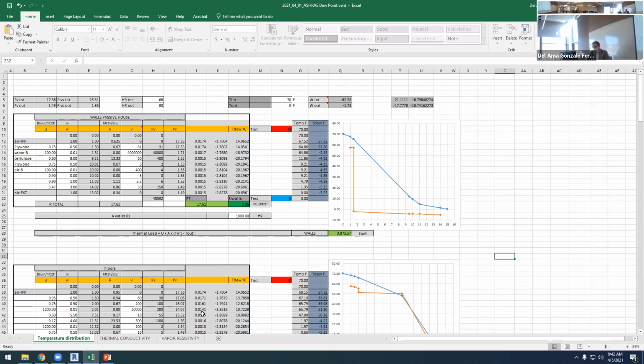There are some people that say it doesn't matter, so you don't have to use vapor barriers. Well, people here use air barriers outside because it's obvious that if the wind is blowing in winter, there will be infiltration issues. So they prevent infiltration issues with the air barrier. That's fine. But I would use the vapor barrier inside.